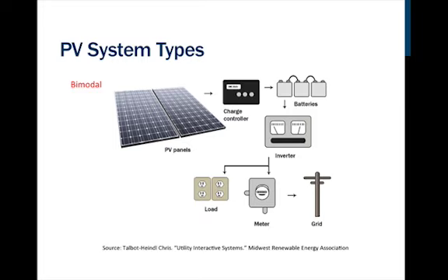You have power all the time, 100% of the time, but it is also the most expensive type of system out there due to the batteries and the inverter. The inverter has to be able to operate standalone and with the utility. Batteries offer a whole other level of complexity that requires more interaction from the homeowner. If you don't check the oil in your car, you're not going to check the fluid level in the batteries. That's really important. The number one killer of a system like this is no participation or little participation from the homeowner. So you have to participate with this system and do service work on it on a monthly basis.